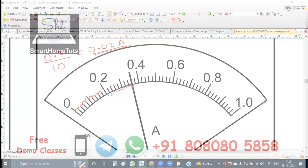Already here this 0.2 is there, plus 8 steps of 0.02. This is going to become 8 multiplied by 2, 16, that is 0.16. So this we will add, 0.16. This reading is going to become 0.36 amperes.